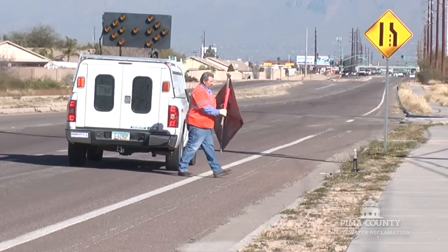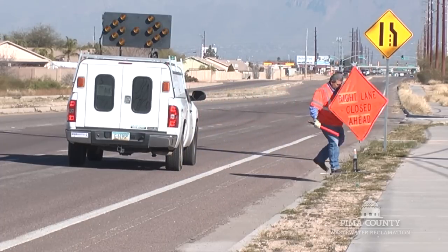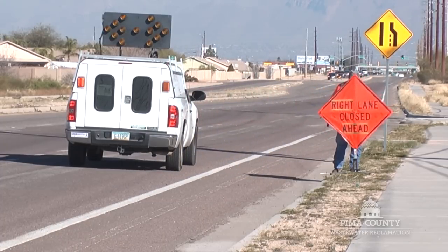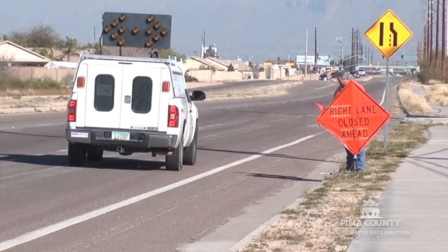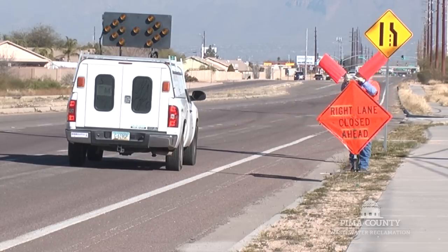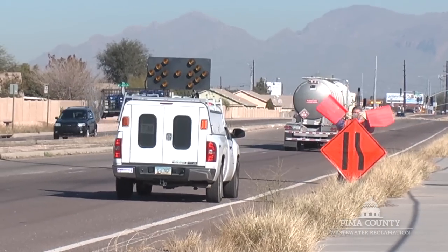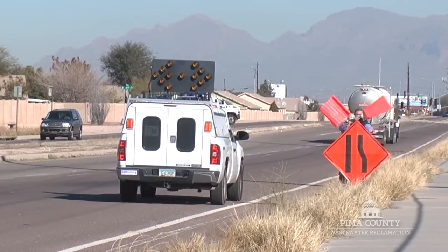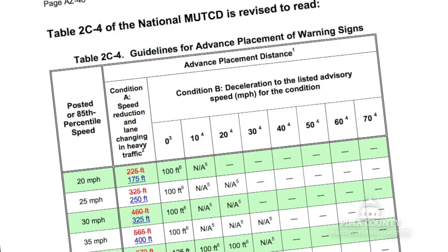The initial signs should be visible from a long distance and should be located in front of hills or curves that may obstruct safety zones. If needed, additional signs should be placed for good visibility. The distance of the sign placement varies depending on the speed limit of the road. This information is covered in the MUTCD.